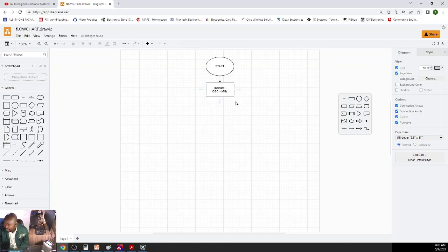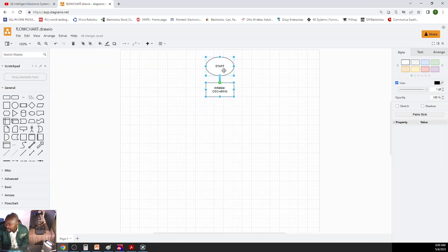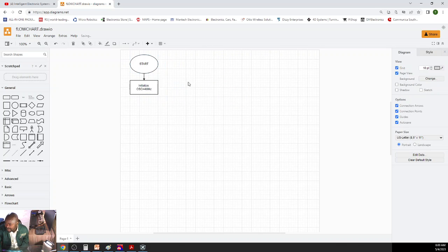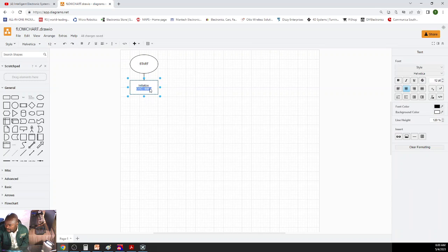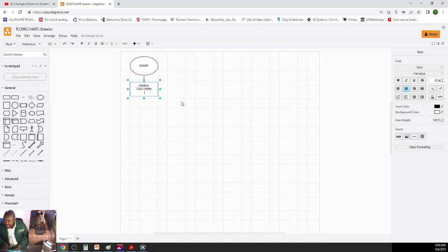Go back to our program. This is the program we did. Now, what I can add here as well is that we also set up our watchdog timer to time out at 2.097 seconds.